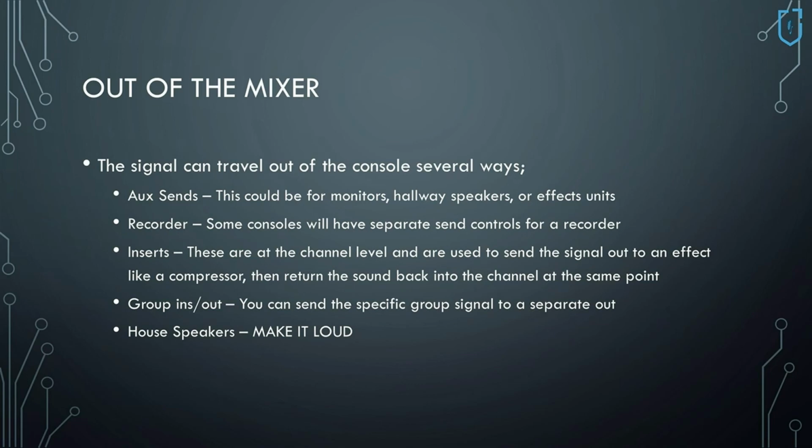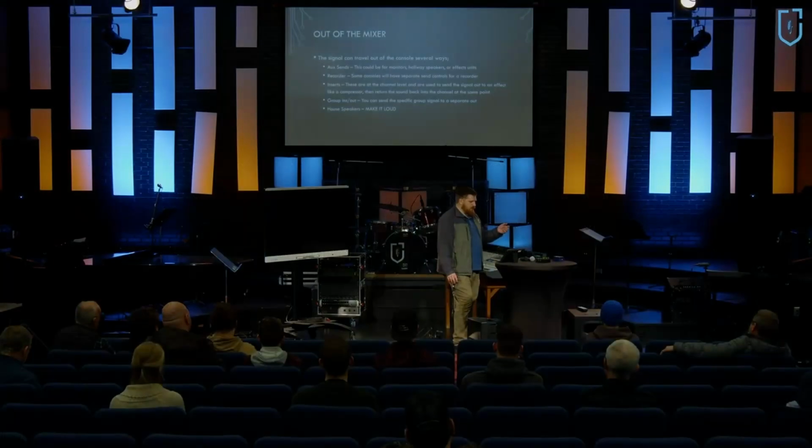Inserts, a few of us were talking about that last night. It's a way to take the signal out of the board to something and then back in again. So that's how you would use a compressor on an analog board. You'd use the insert point on the channel. It would go out to the compressor, back in, and then it's now a compressed signal.